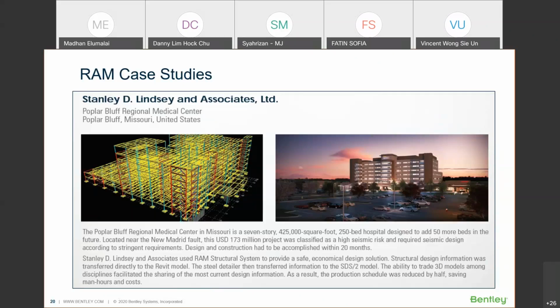Shear walls in concrete buildings are meant to take shear load, which is coming in from lateral loads, isn't it? Same thing for steel structures is bracings and moment frames. So this facility of modeling gravity and lateral members in RAM Structural System makes this program unique in the building industry, which we generally don't see in general purpose analysis programs.